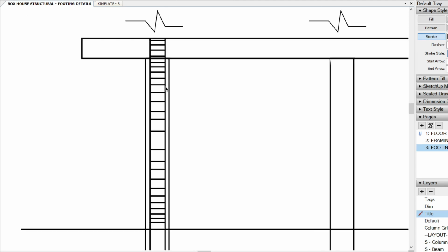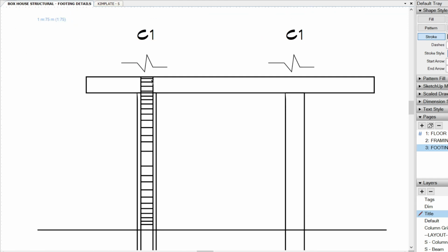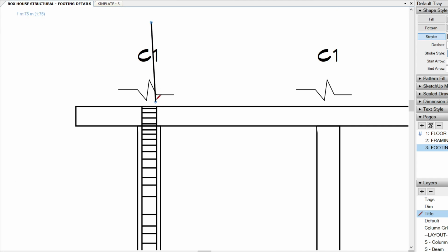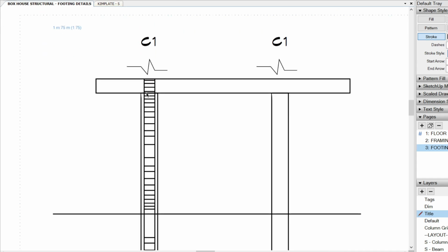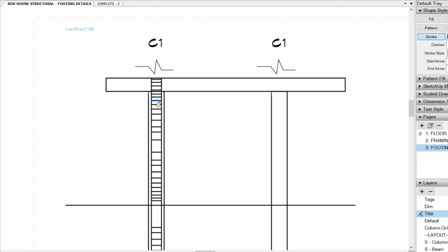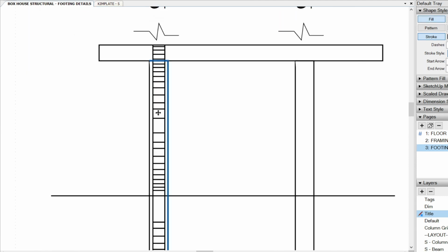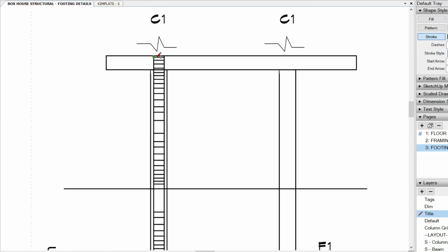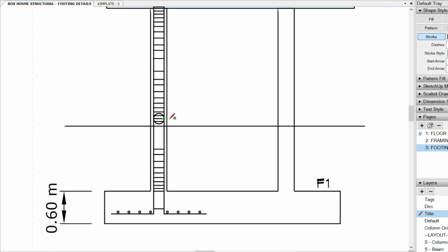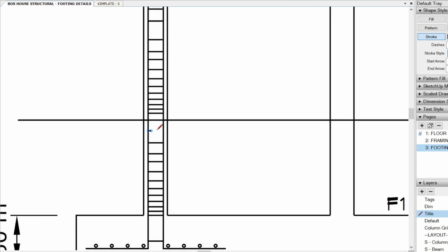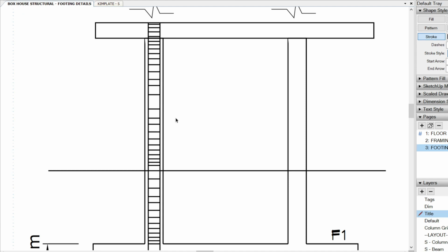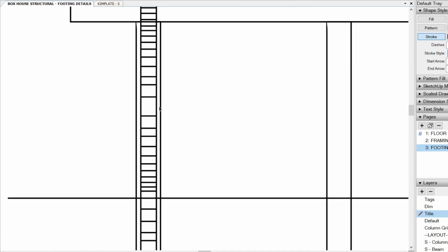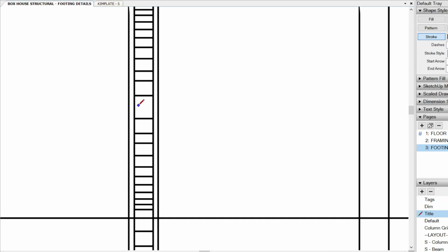Anyways, the main point is that the closer the reinforcement here, the better the reaction to compression. That means load going down. And since concrete is a compressive material, while steel reacts best to tension or pulling, then we really have to take care of our intersections. Okay? So usually our other ties are like, the rest go 20-20. That's 20 centimeters or 8 inches until they reach the middle, so +1.